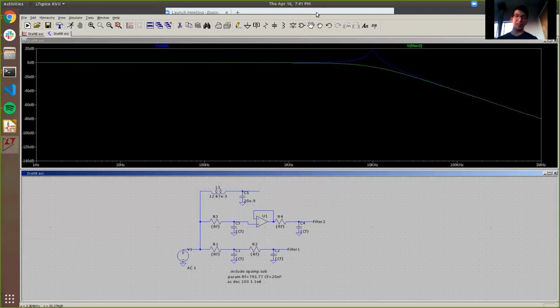Sometimes your signal isn't going to have a lot of current, so you can't justify that much space if you don't actually need to, like if you're not filtering power, for example. Which is why you can use a basic RC filter for your low pass filter requirements. Does that make sense? It all comes down to space and cost.